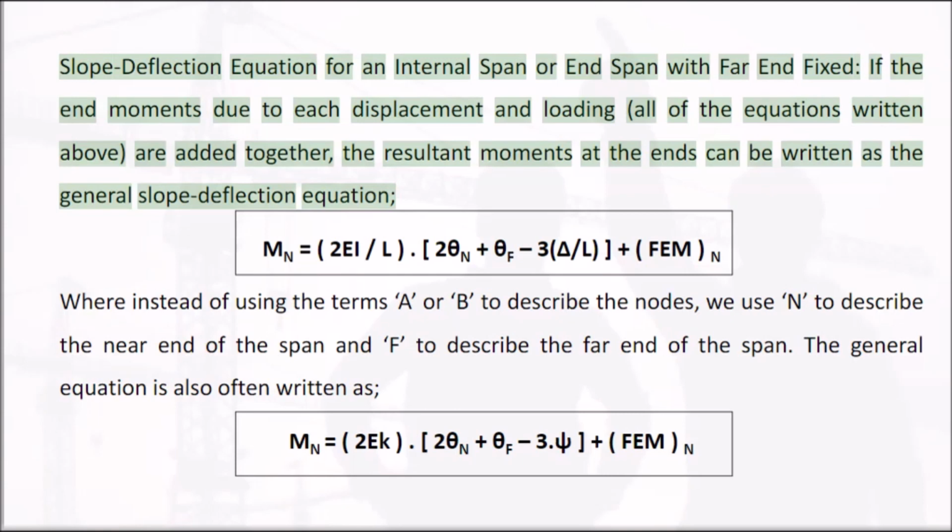Slope-deflection equation for an internal span or end span with far end fixed. If the end moments due to each displacement and loading, all of the equations written above, are added together, the resultant moments at the ends can be written as the general slope-deflection equation.